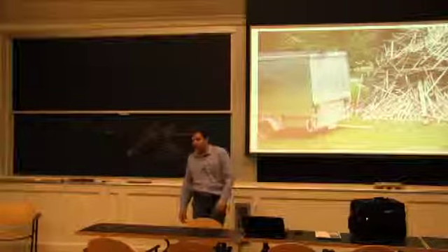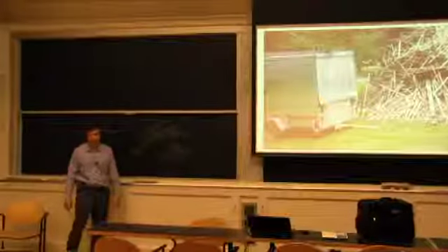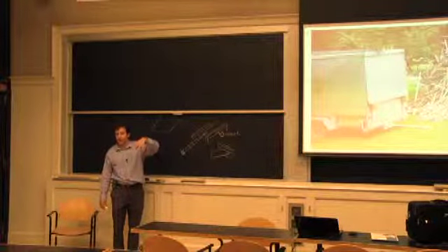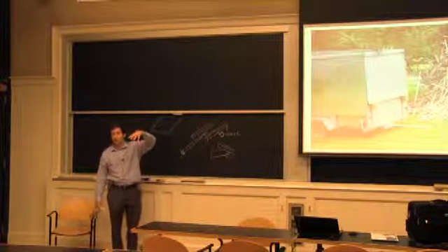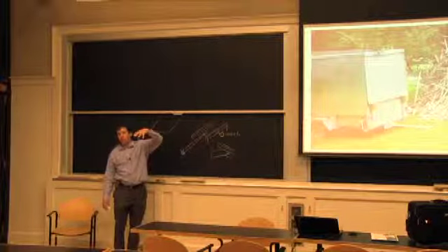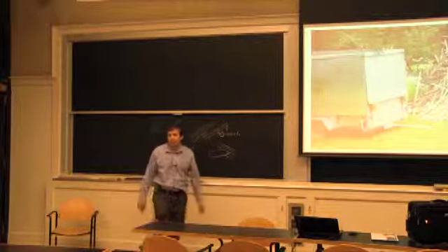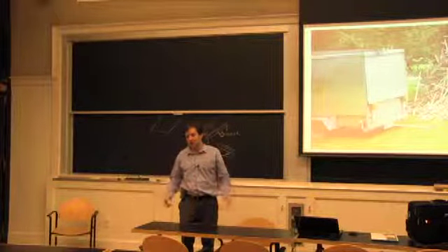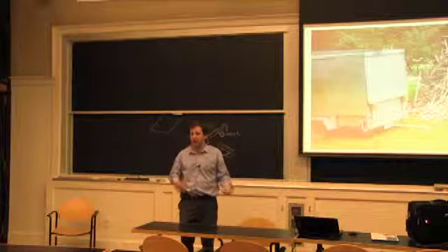In addition, I said, okay, so I have 2,000 pounds in it, so if I start lifting the roof and for whatever reason there's enough suction to take 2,000 pounds, well, I don't want the whole thing to take off, so it's got to be able to take 2,000 pounds of pulling force. So we can fill it up and lift it until the wheels untouch the ground. Just with the idea that I didn't want to deal with all of the aerodynamic issues.